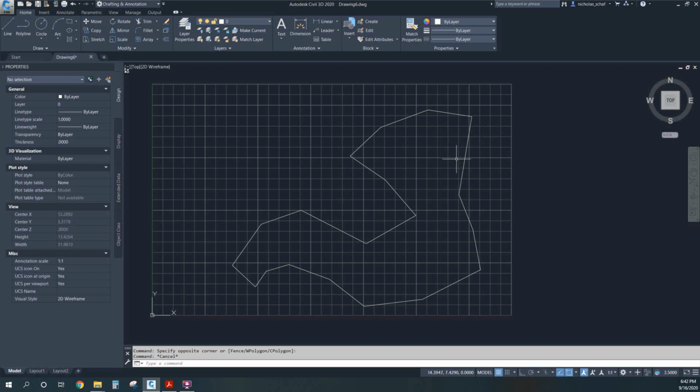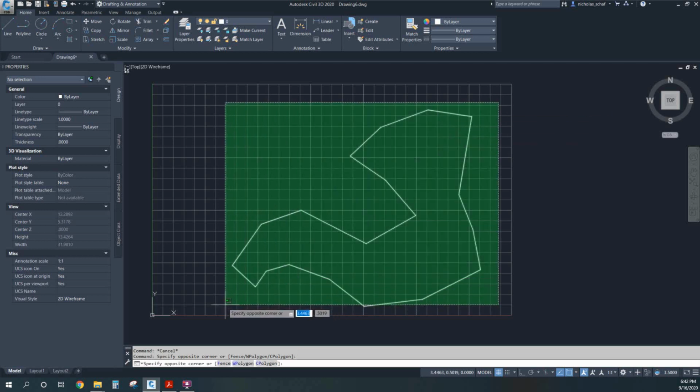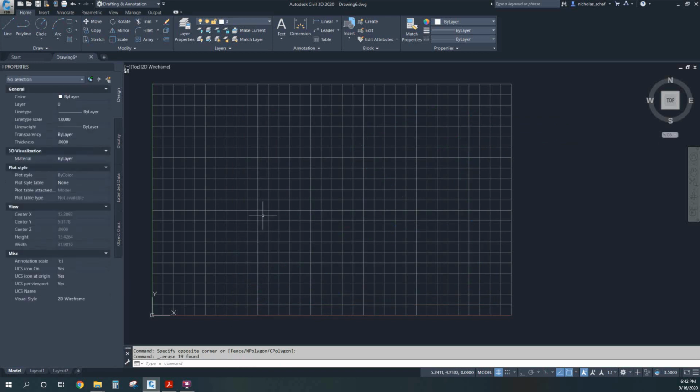So that also goes along with the continue. That allows you to continue drawing the line. And then that's the line command. So I will go over those buttons in the command line now. So another way that you could do it, because there are hotkeys in AutoCAD that you can press on your keyboard to start various commands. So if you type in L, that starts the line command.